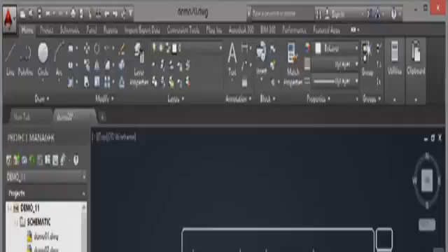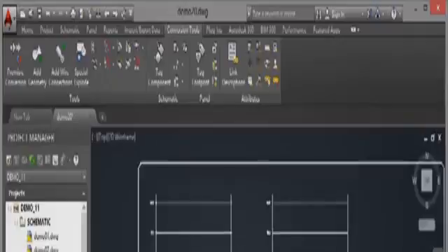Let's have a look at converting non-AutoCAD electrical objects, such as text, into AutoCAD electrical objects that we can use with our ladder. What we do is we go to the Conversion Tools tab on the ribbon, and we use this icon here, Convert Ladder. It converts non-intelligent ladder line reference numbers to those compatible with AutoCAD Electrical. So if I click there and come into the drawing area, it prompts me to select the objects. So you need to select first the ladder reference text objects.